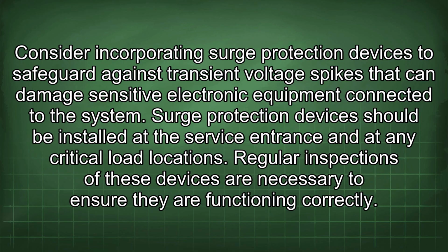Consider incorporating surge protection devices to safeguard against transient voltage spikes that can damage sensitive electronic equipment connected to the system. Surge protection devices should be installed at the service entrance and at any critical load locations. Regular inspections of these devices are necessary to ensure they are functioning correctly.